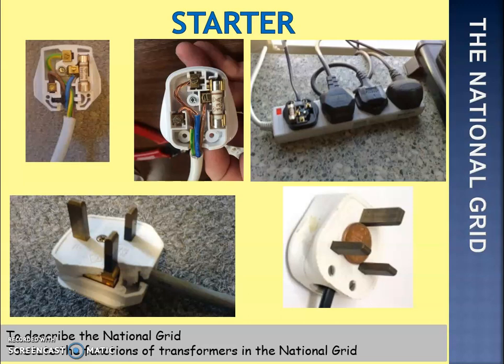That insulation, the coloured blue, brown and green and yellow, should go all the way to the ends of those wires. So that would be a dangerous plug to use. It could cause an electric shock. As would the one on the top right hand side. There's no back cover to the plug, exposing those wires. So again, it's not one that you should use.